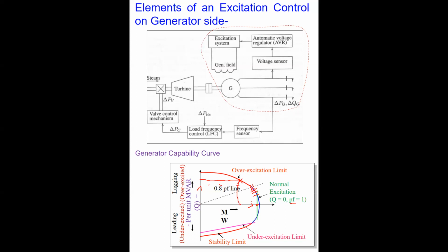Can you say? That means you're supplying lagging reactive power, or you have less active power supply, but you have more reactive power supply. But the generator has to supply active power, although some amount of reactive power is required. But again, if you have this operating point, what will be the power factor? It will be less, poor, maybe 0.7. Poorer, right? Because the generator is meant to supply active power basically.